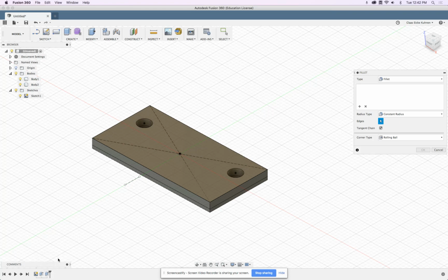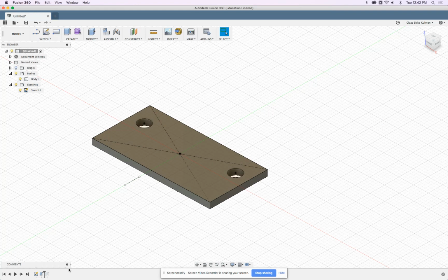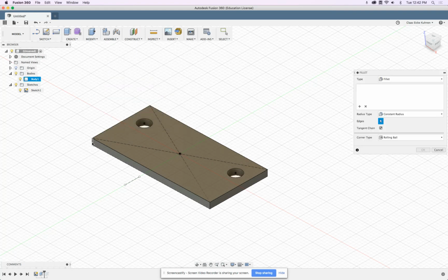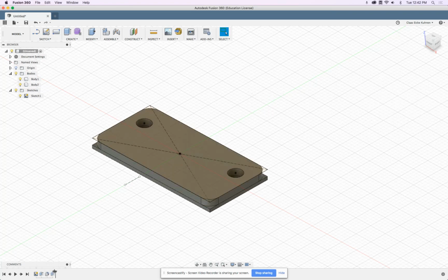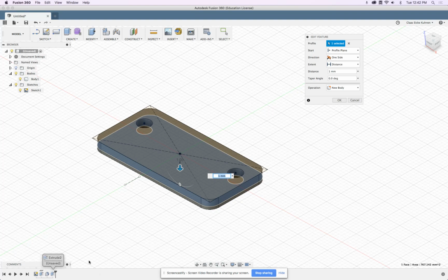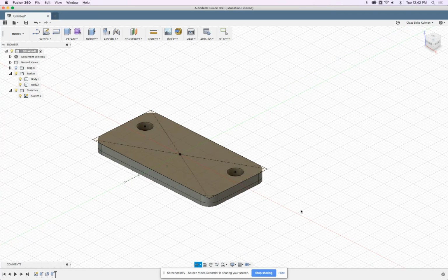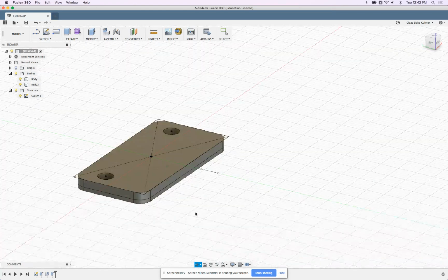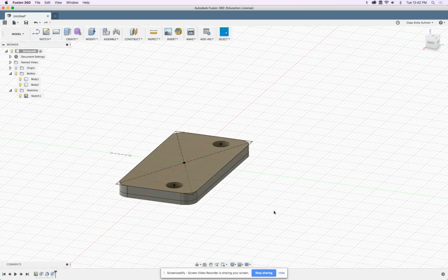I could also make it a little bit easier for myself and say I go to here in the timeline, then I round these 4 edges by 3 millimeters because the extrusion should, but does not. Naughty, naughty Fusion. So one time right click and edit, refresh it, and there it is. So you see that this way it just copied the fillets.